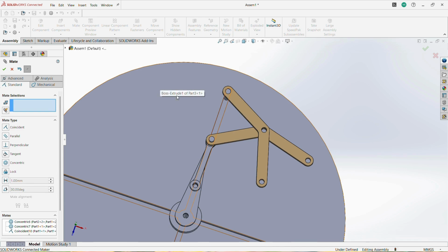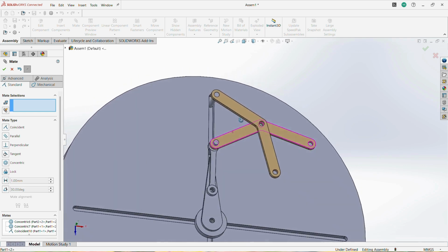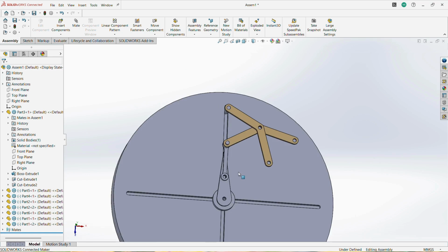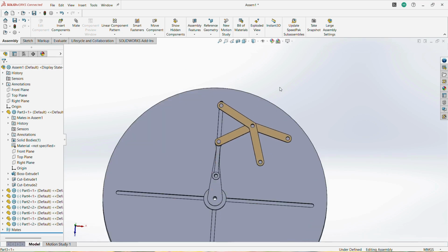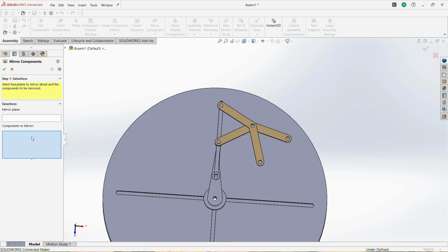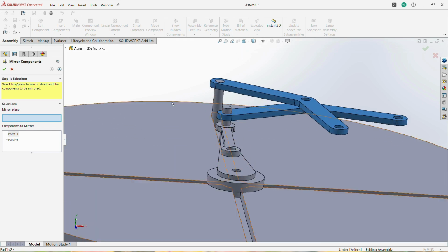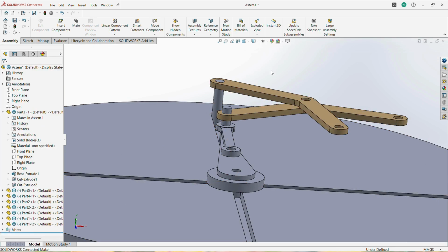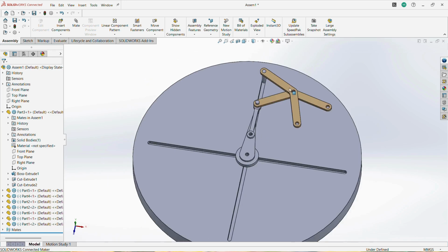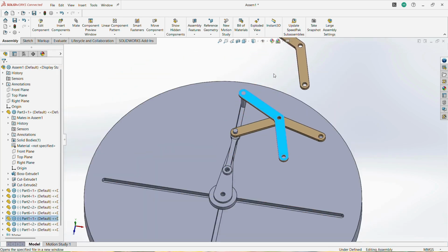Okay, this is how it gets now. Yes, almost we got that. Either we can use a mirror component to mirror these positions from the right hand to the left hand. But if you mirror the component and change the positions, we cannot get the proper output, based on the selection of plane also. So instead of using a mirror component, use the same kind of part, twist it and mate it properly. So first select this part, hold your control button, duplicating the part first.